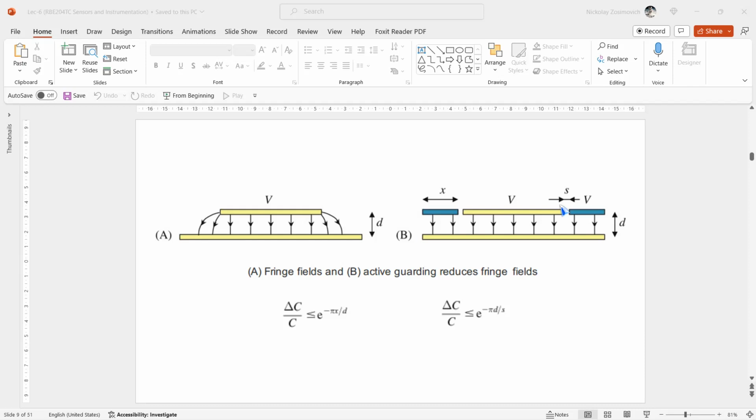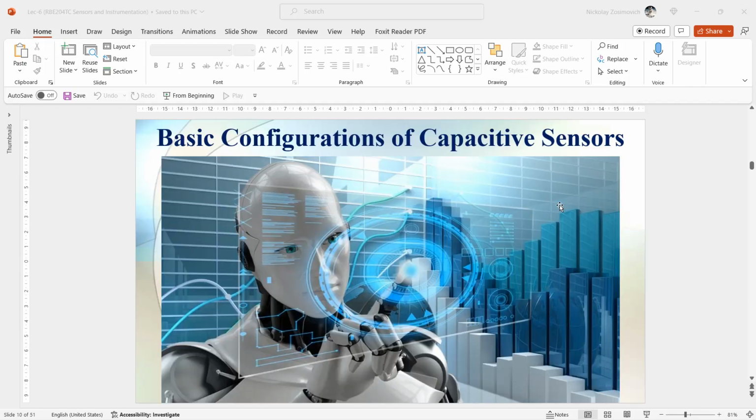Capacitor sensors are very useful for the measurement of displacement, utilizing variation in the geometric factor G. If one of the plates is part of a deformable membrane, pressure can also be measured by using the capacitive principle.